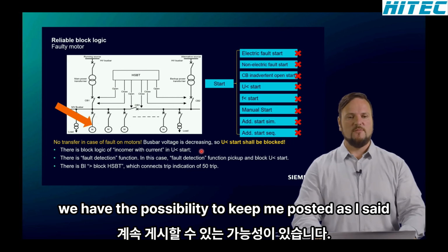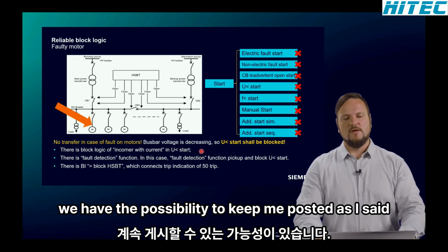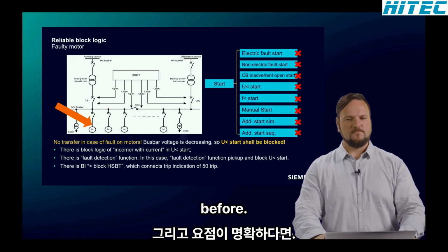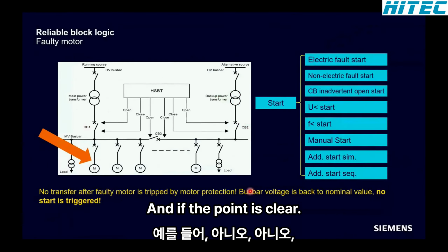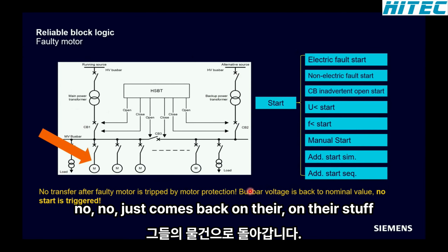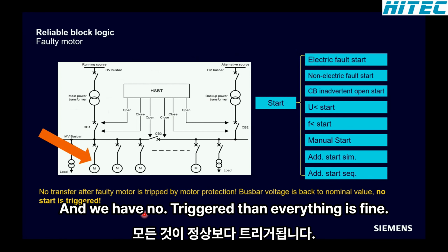Additionally, we have the possibility to use the binary input here, as I said before. And if the fault is cleared, for example, the voltage comes back on the motor bus, and we have no start triggered, then everything is fine.